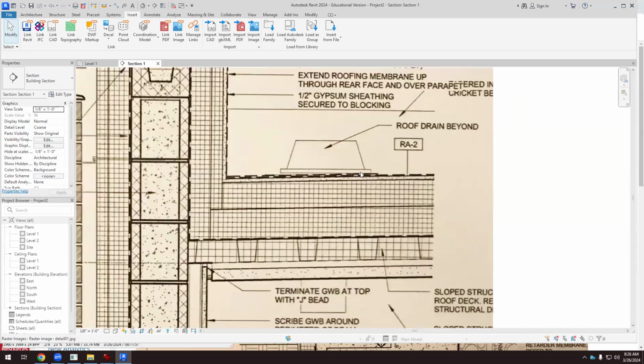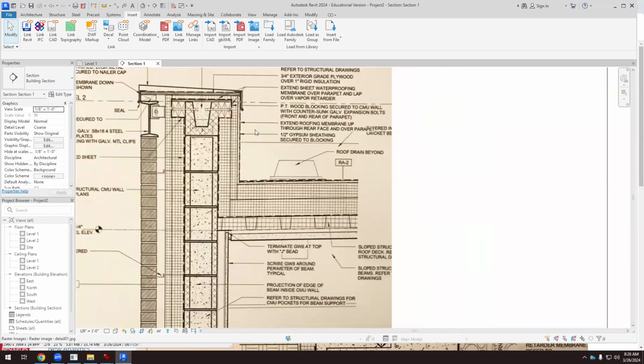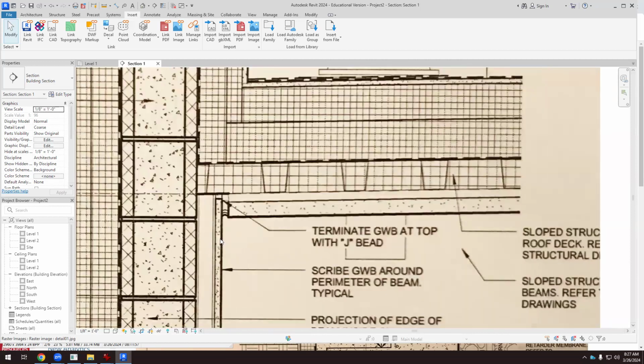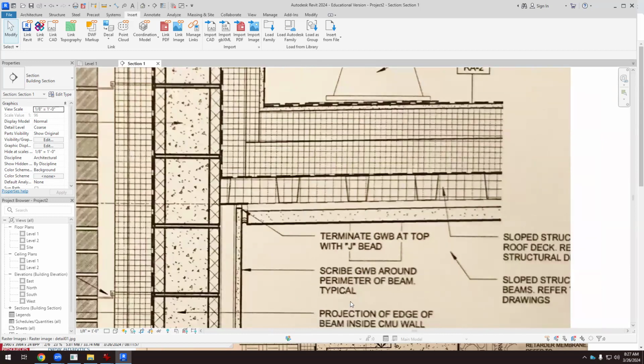And then we have all these layers, all these membranes. They are water barriers, air barriers. The key thing is the continuity of all these. And then we overlap, okay, so I think it's a good detail. So we're going to copy this detail. The finish, this is the gypsum, the GWB is a gypsum wall board. I think it stands for that. And it's this material, here, the drywall or the gypsum wall. And that's the false ceiling, okay?